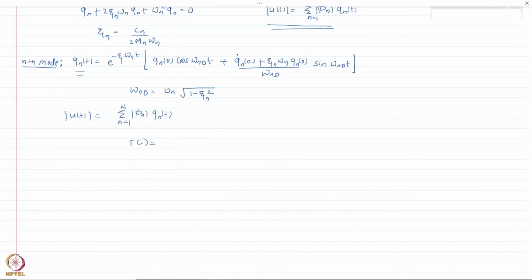So what we typically do for practical analysis, we assume or we determine experimentally the damping ratio for each mode, because remember now the damping is defined for each of these modes. There are some experimental methods to do that, or we can assume some values based on the data that we have observed in the past from the testing or the response of other types of similar structures.